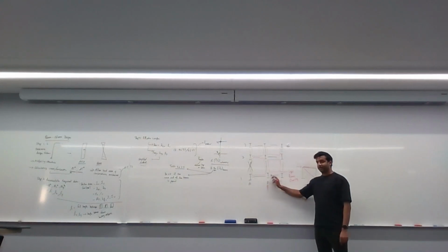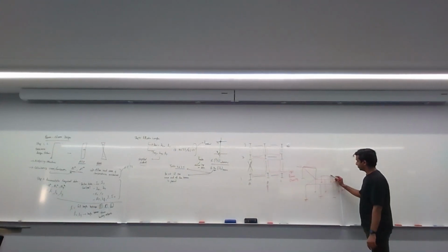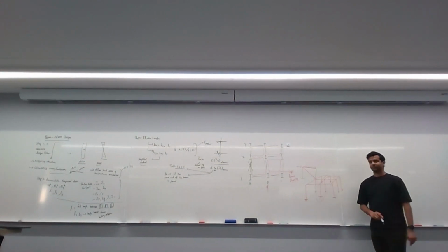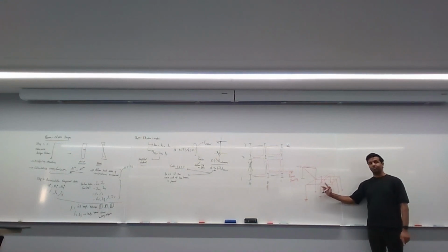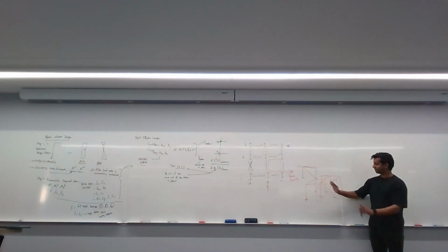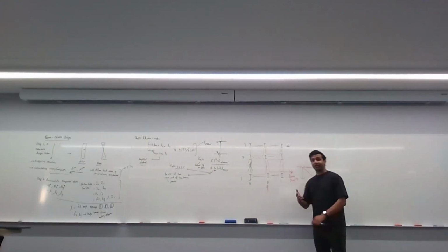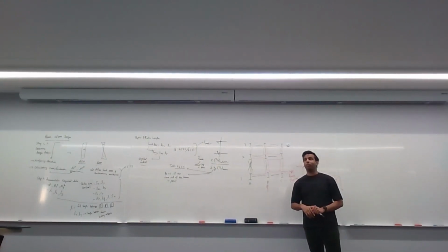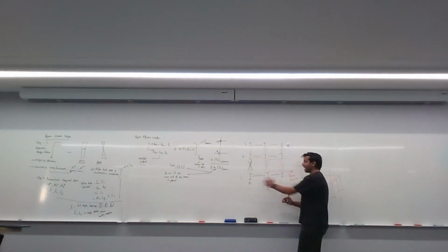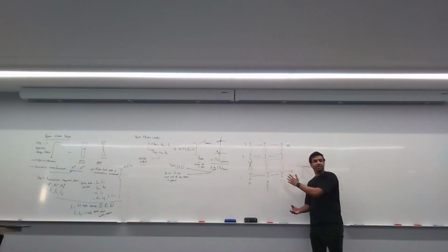When I'm referring to frame B, in this case, I'm referring to this frame. That's frame B. And I'm asking you, is frame B braced against movement like that? The correct answer is no, it isn't. It's a sway frame. Why is B a sway frame? Because A is a braced frame. B isn't braced, there's no bracing here. C is also not braced. There's no bracing here.